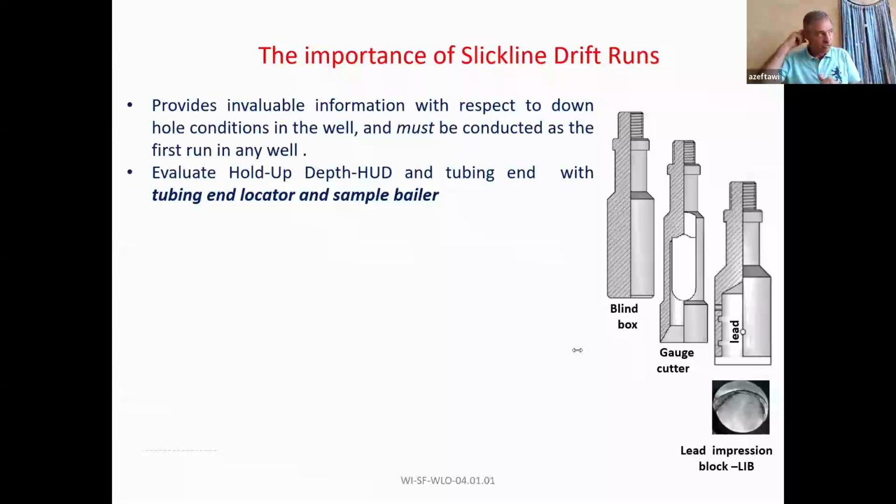I also mentioned that when we rig up coil tubing, all connections from the Christmas tree all the way up to the sky have to be flange to flange. Because flange will withstand the torque, while thread does not. So in wireline, we still use a lubricator. In coil tubing, we cannot use a lubricator. We have to use risers.